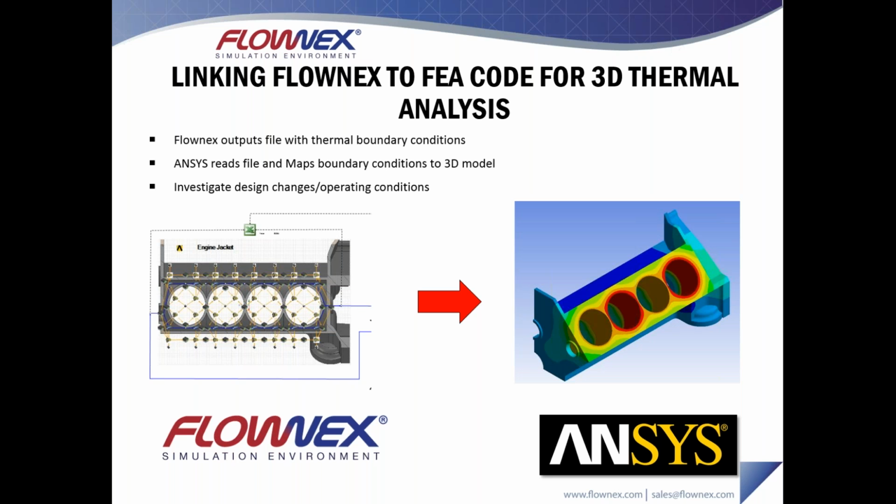How you would typically do that is you would have Flownex output a file of thermal boundary conditions, and then you would have your FEA tool, in this case ANSYS, read and map those boundary conditions to a 3D CAD model.